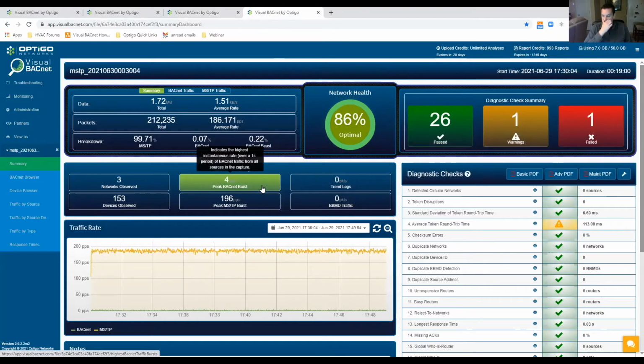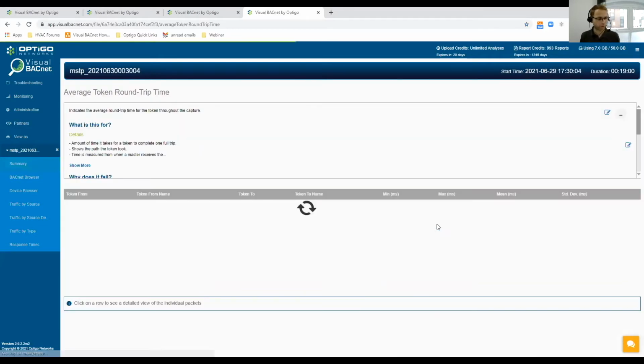So once you got a little bit further down the path, and once you isolated the pumps, was that the only 2 devices you had on the network, or did you remove them from the network and then this 86% score was the final result? I would have to see how many devices that one's got. Seeing in total, I think that's with everything back together. But once we isolated that down, it was these pumps. We were then able to go down even further and just connect one pump onto the router with Visual BACnet and take a quick capture with that one device in isolation.